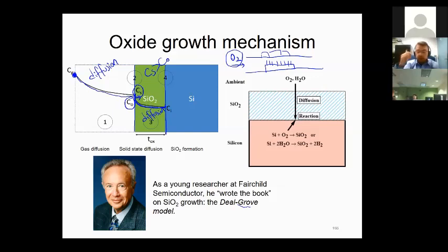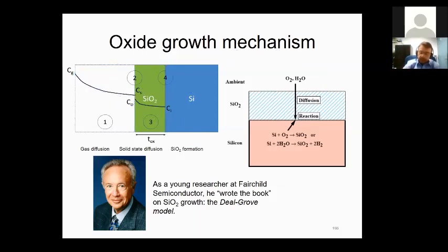So shortly, the oxidant should go through all these steps, should go down to the silicon layer to start the chemistry. As the fourth step, it goes down there and reaches this concentration, and it starts breaking the silicon bonds. What does it do? It replaces them with oxygen. Okay, and that's how the silicon dioxide is grown, from bottom to the up. All right. So that's showing you the two ways the silicon dioxide reacts with oxygen and water vapor.